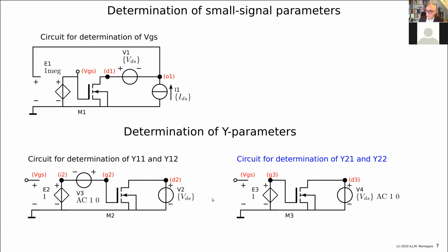So we still bias it in the correct way. This is a gain of unity, just copying this source, so you don't have to type in the digits, just copying this voltage that is generated here. So that means that this is exactly biased as we did here in this model. This type of model-based biasing, you could call this. Here we have a model for biasing. Here we copy the parameters to our circuit. So this is biased in a similar way, exactly at the same voltage, because that is just the voltage we connect, and the current will be exactly the same.